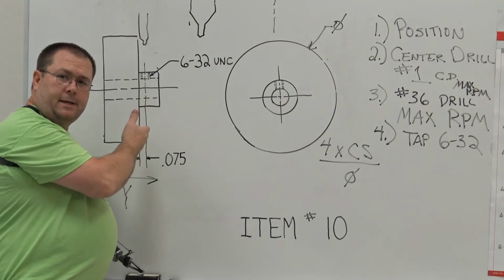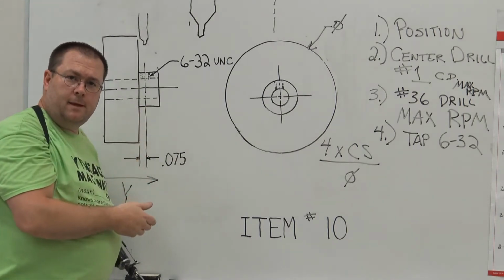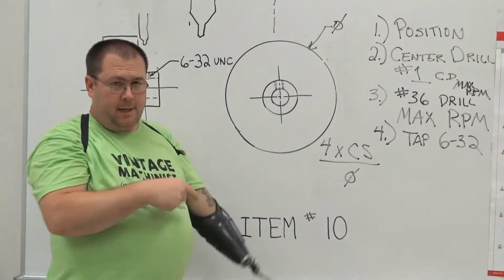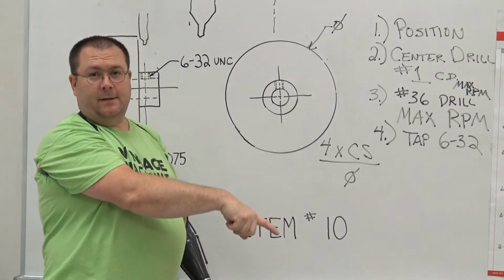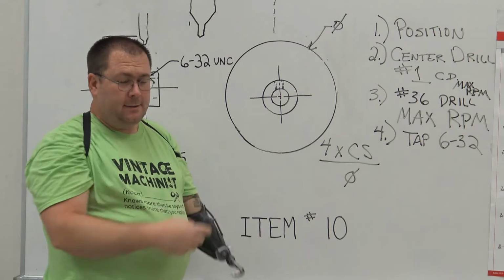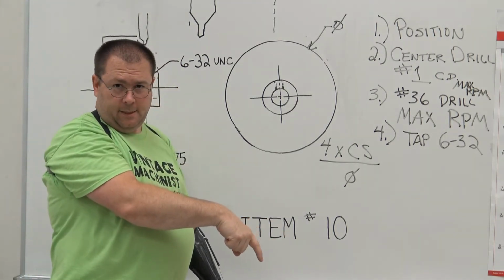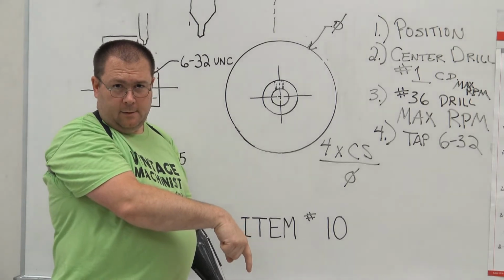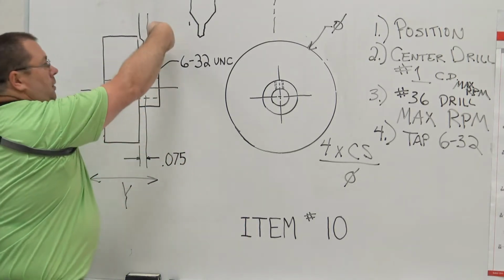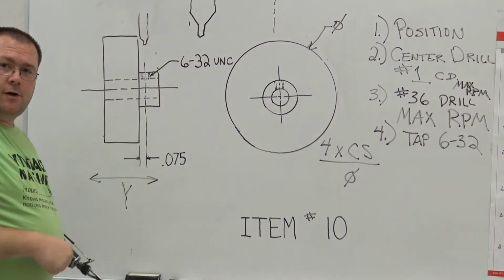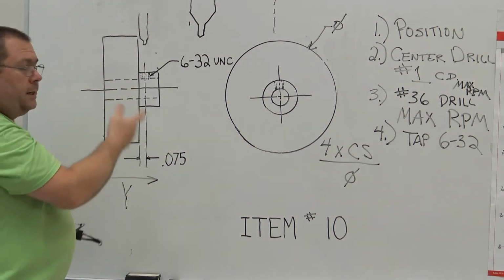The same thing exists with a tap. It's pointed on one end and you can see the thread, but just because it's pointed and it points down in the hole where I'm cutting the threads doesn't mean that it's going to cut straight into the hole, right? So if I start tapping the thread crooked, it's going to finish crooked. So we're going to constrain it.